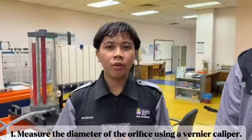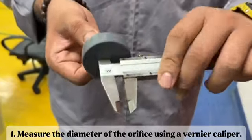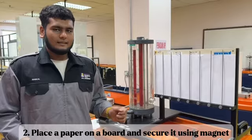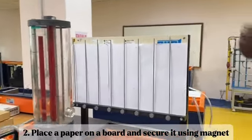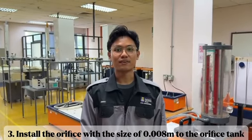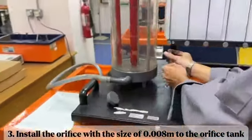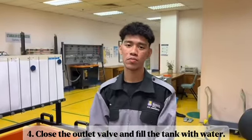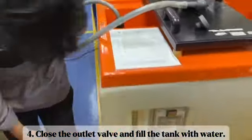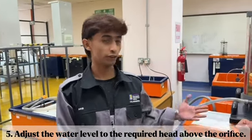Firstly, we measure the diameter of the orifice using a vernier caliper. And then, we place a paper on the board and secure it using the magnet. And then, we install the orifice with a size of 0.008 meter to the orifice tank. Then, close the outlet valve and fill up the tank with water. Adjust the water level to the required head above the orifice.